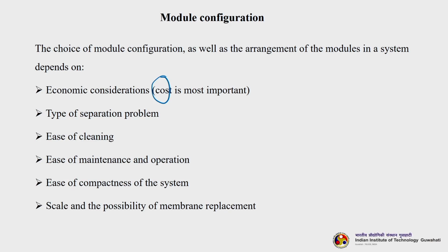Then ease of cleaning is another parameter which should be considered while designing a module. How easily can I clean a membrane? Because as time elapses, there will be concentration polarization and fouling. To get rid of these we need to clean the membrane, either by using backflushing or some other techniques. To do that I must disassemble the membrane module, and the module should be easy to assemble and easy to disassemble, then cleaning will not be a problem.